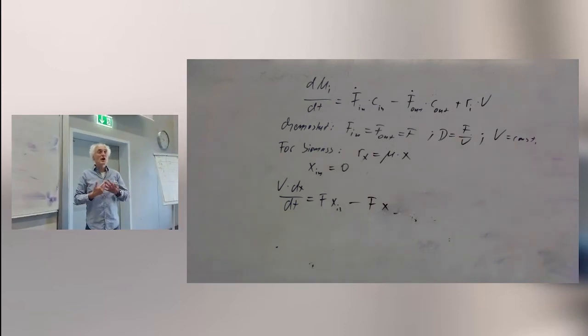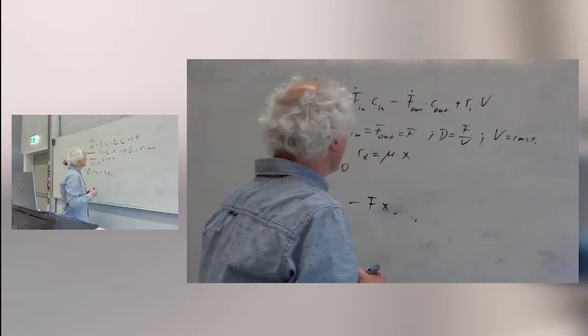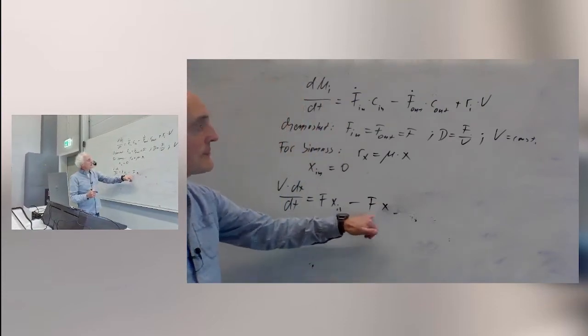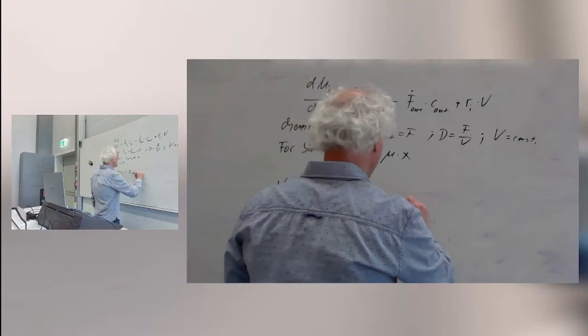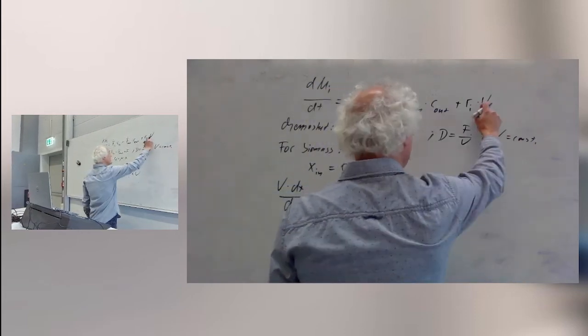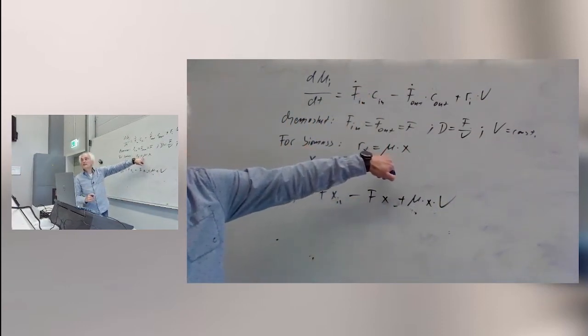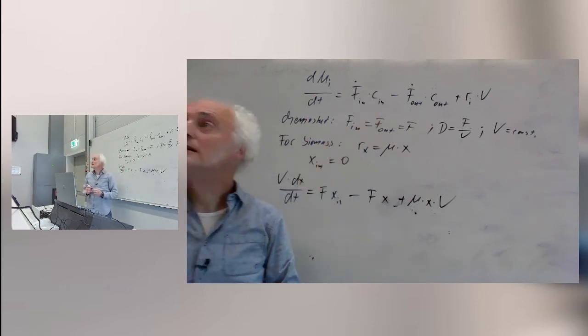And of course, we think of optimal conditions where we have an even distribution, which usually is the case. This assumption is quite good. It's close to reality because we need to put in the gas anyhow, so we will have rigid agitation in our bioreactor. So we have F times X, this is what's going out, plus mu times X times V. Now we don't forget the volume here. So Rx again is mu times X. So we just put everything in here.